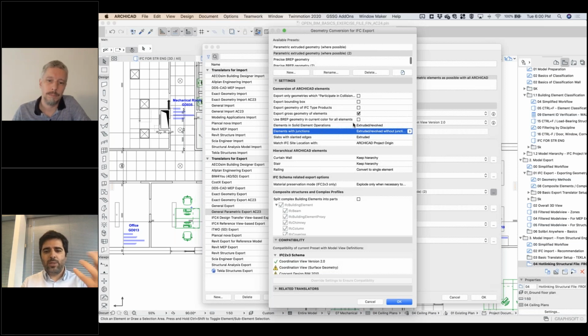And then on the receiving end, they would have to import all the extruded elements and then put on top all the BREP elements. So it doesn't mean that we translate everything just in words. Some things we translate with gestures or with a drawing. It's the same thing here. Sometimes we have to export two or three different parts of the model and then assemble them so that we bring them in with the best translation possible.